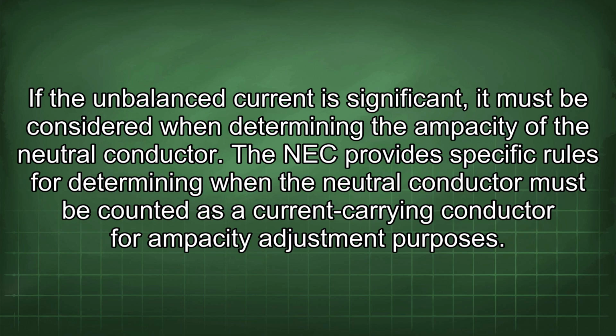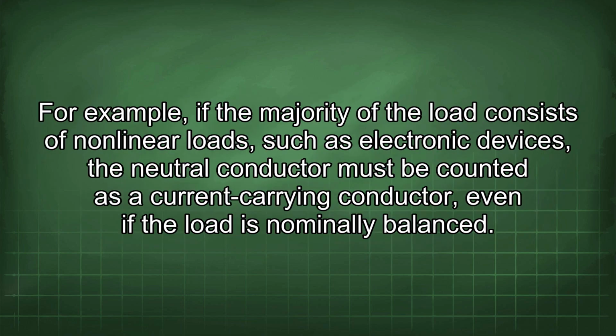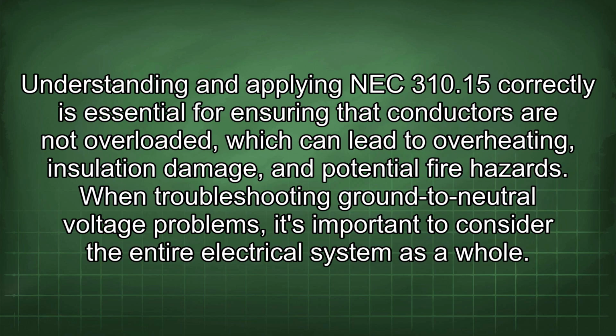The NEC provides specific rules for determining when the neutral conductor must be counted as a current-carrying conductor for ampacity adjustment purposes. For example, if the majority of the load consists of nonlinear loads, such as electronic devices, the neutral conductor must be counted as a current-carrying conductor, even if the load is nominally balanced. Understanding and applying NEC 310.15 correctly is essential for ensuring that conductors are not overloaded, which can lead to overheating, insulation damage, and potential fire hazards.